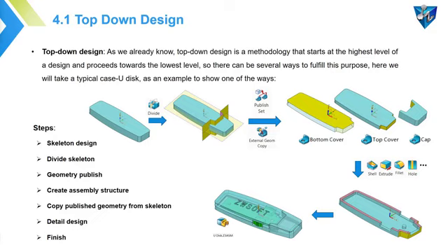So step 1, you need to design the skeleton, which is the outline of the U-disk. And step 2, we need to divide the skeleton into several parts. Now, there are some sub-steps which we will cover later in the software. And step 3, we need to do the detailed design one by one. And the last step is assemble all the parts together. Okay, later I will show you this case in ZW3D.